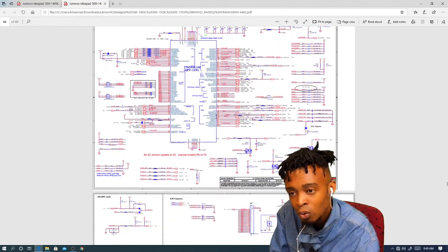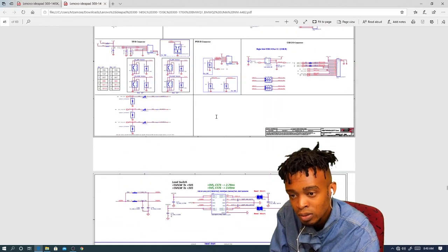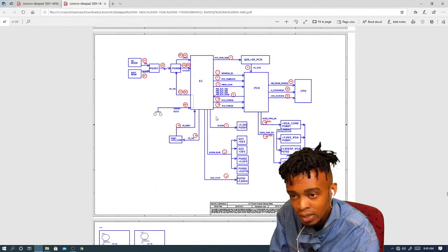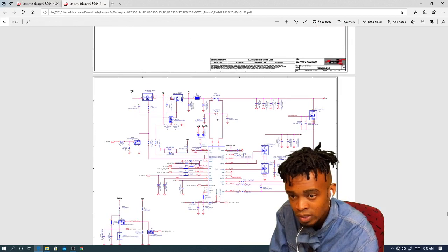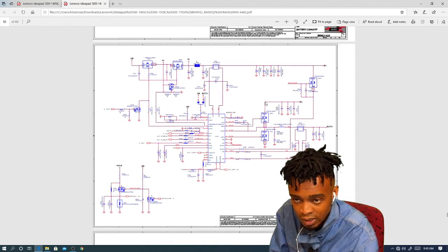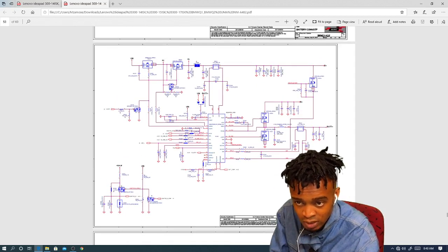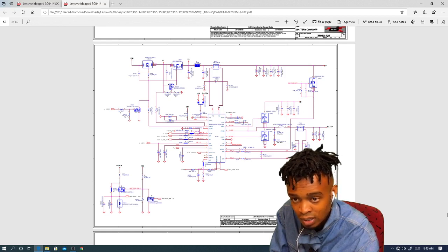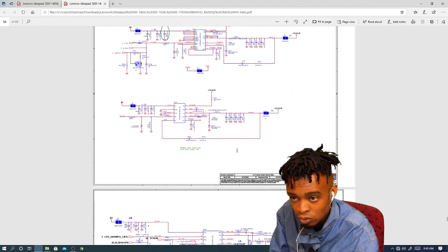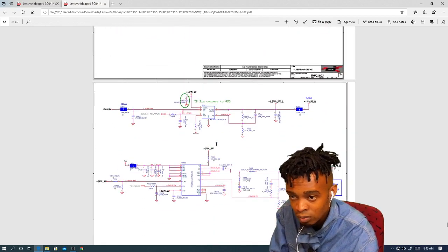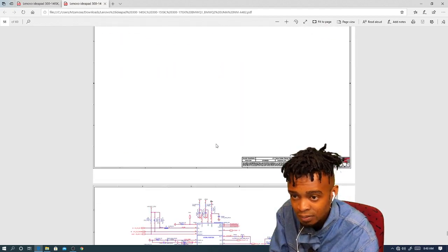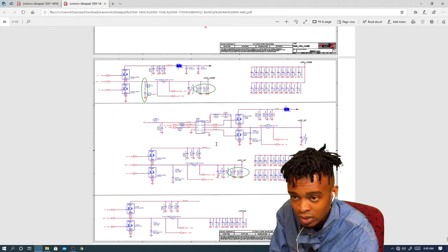Remember, on the old motherboard, normally how do we get 3.3 and how do we get 5 volts? Usually we use two MOSFETs, right? We use two MOSFETs, one connected to ground and the other connected to the main power, and there will be a chip controlling those two MOSFETs. This chip generates 3.3 and it generates 5 volts using different MOSFETs. But in this case, we don't have MOSFETs.